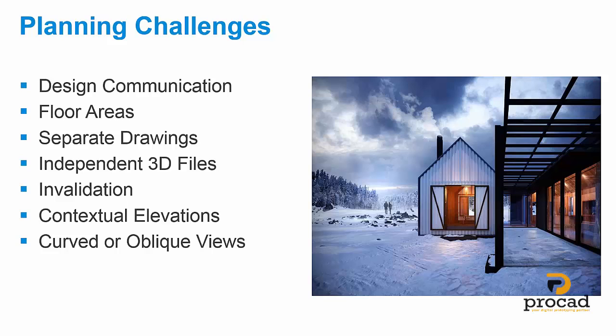Having design drawings that were created or saved in a different folder and don't relate to necessarily design updates of the floor plan in relation to the elevation. And then we've all seen invalidations in planning applications which we don't want to see, which can happen from missing information on drawings. A window is shown in a floor plan but it's not shown in an elevation. This can all happen within a traditional process.